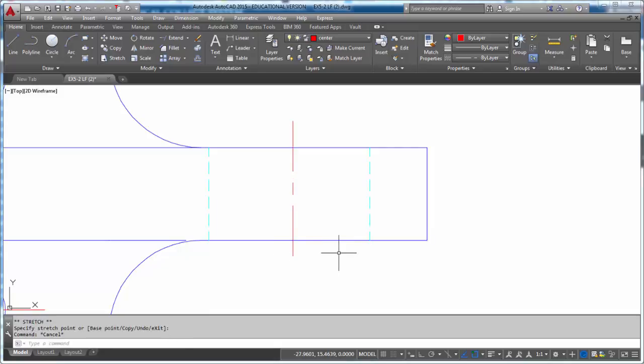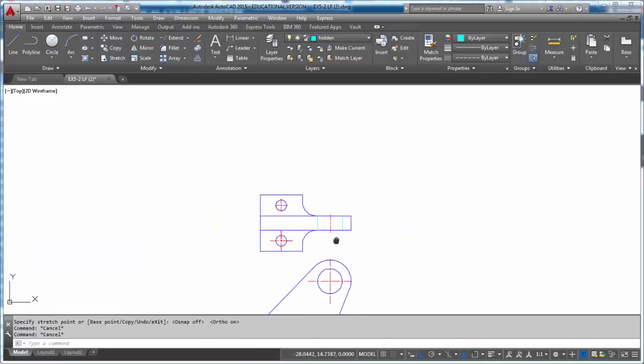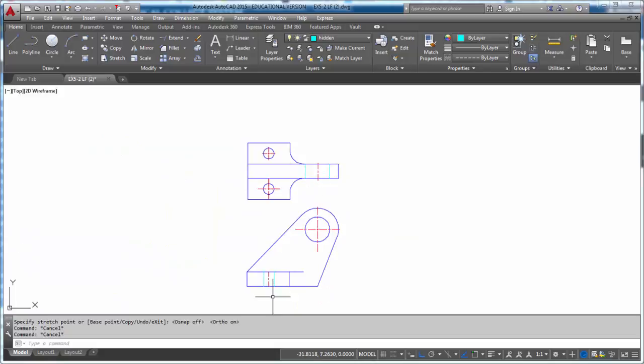Okay, so center line should always go past the edge, that is, center lines for side views of a hole should always go just a little past. You might want to turn on ortho. So something like that. Okay, and make those changes and resubmit it.